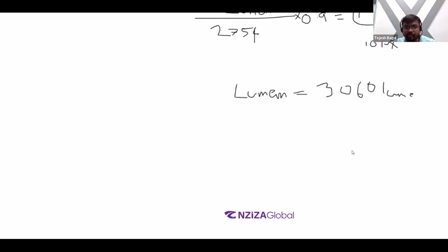All right, now we'll start placing the light fixtures based on the given path of egress like this. From this point, we will have the light fixtures going this way, and from the last point, we'll keep it going this way, since this seems to be the closest possible path of egress. Let's take this one. We'll create similar, and please note that we will place it on the work plane, the same work plane we were working on, first floor ceiling. We'll make sure we start laying out the light fixtures.